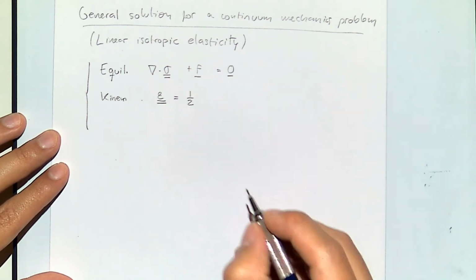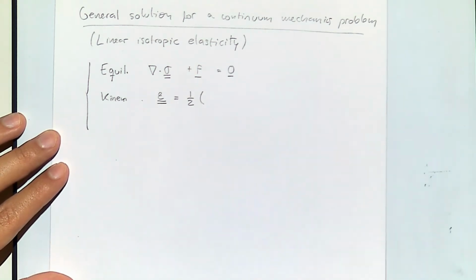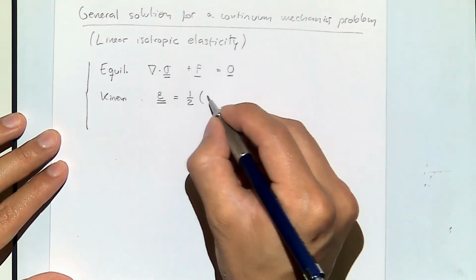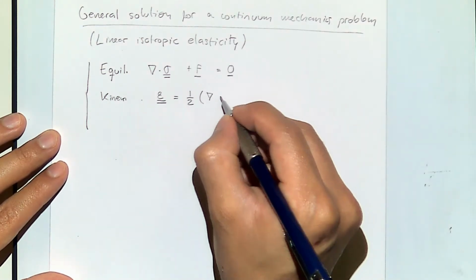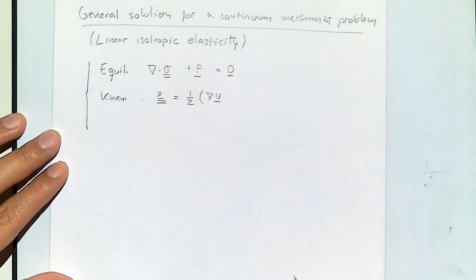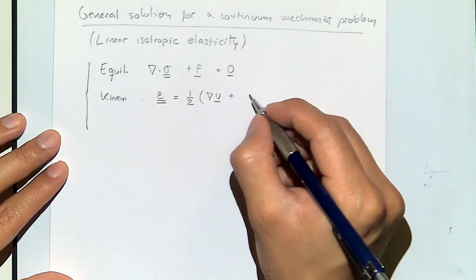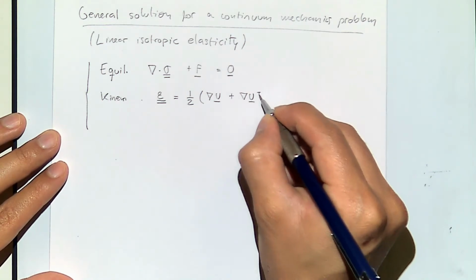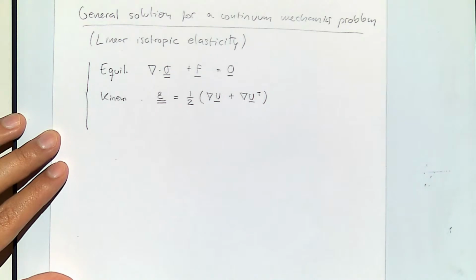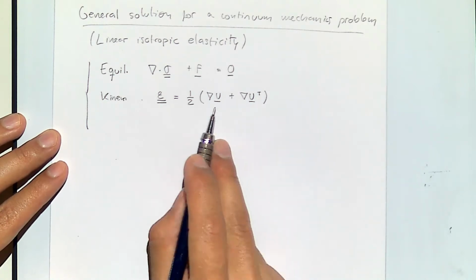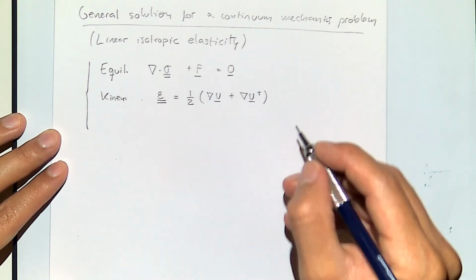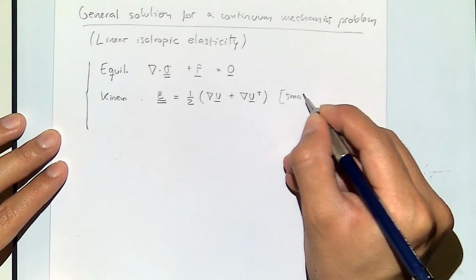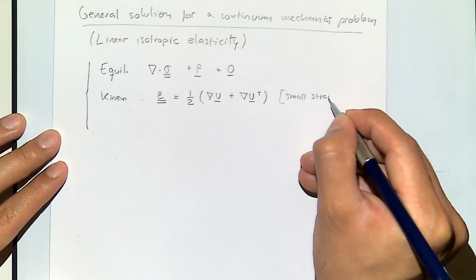We can shorten this equation, instead of writing all that big matrix, with this vector notation that you don't have to remember by heart, but here it's a lot more useful to write it in a compact manner, where this T means transpose. But basically it tells you what strains are as a function of displacements. And remember that this particular equation is valid for small strains.